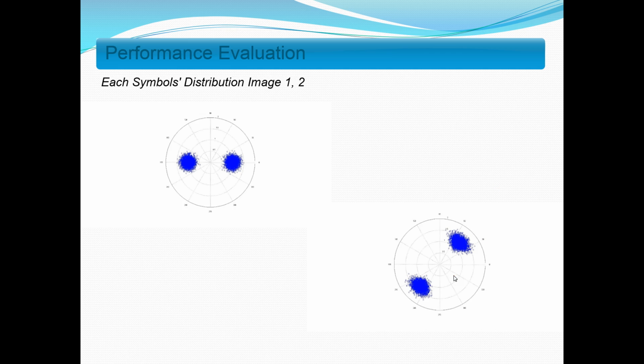We can see that if the delay is longer than the CP, there will be some distortion in the constellation points, which is that the CP really can help us to eliminate the ICI, but it can also cause some distortion to the whole system. So, if there may be some distortion, why should the CP still be used?